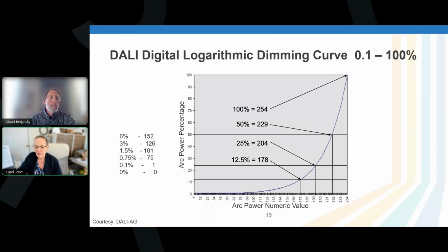Based on our physiology, it looks like a regular linear dimming curve. And that's wonderful. That means that customers can use the dimmer or have settings or whatever else, and it's going to be 50% of the light and 50% of the energy, and you can know that reliably. With a 0 to 10 volt dimming system, you'll probably recognize this: when you're dimming at the wall, there's nothing, and then all of a sudden in the last 20%, you're trying to dim 100%. So this just makes it reliable and consistent.